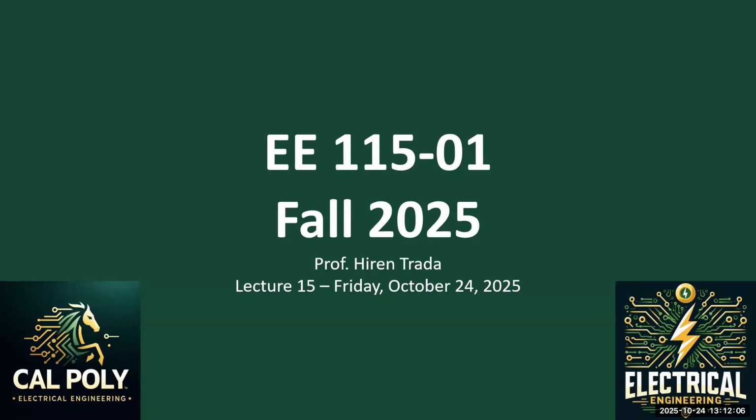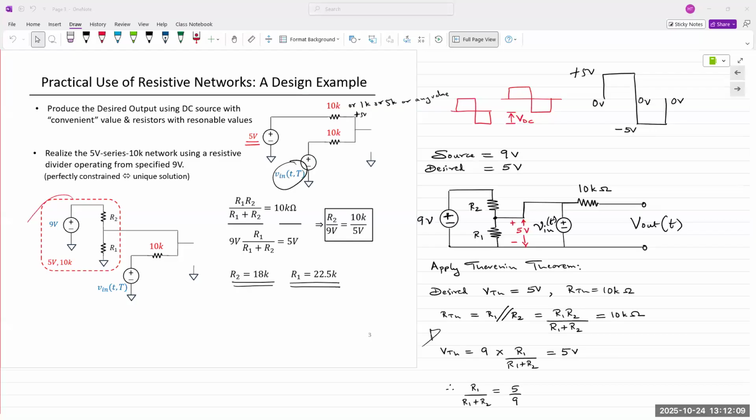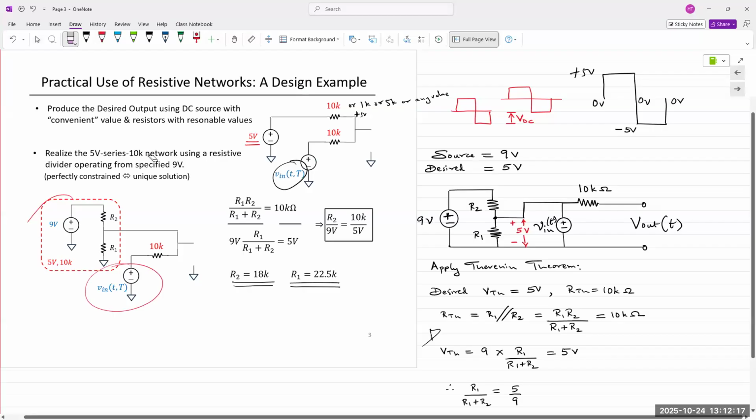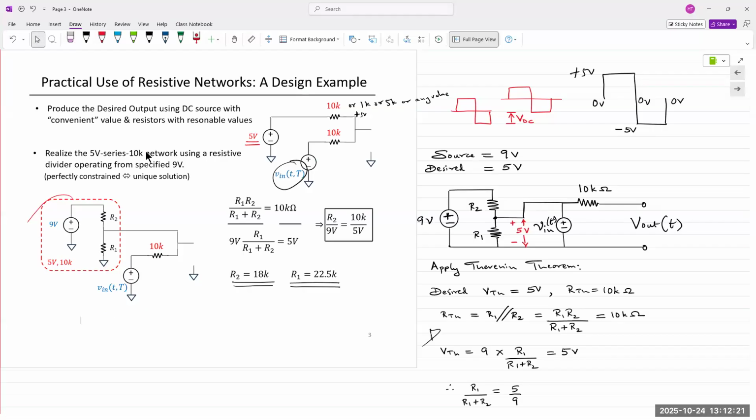All right, this one. The question that was asked was, if we have the signal V in of t that is between plus and minus 5 volts, a plus minus 5 volt square wave, 10 volts peak to peak, and we are trying to shift it upwards. We are combining it with a DC voltage source of 5 volts. How do we know it's 5 volts?